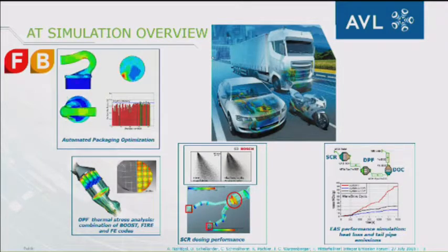Then a simulation solver calculates the uniformity of flow. Value one is ideal uniformity, and we have set a target of 0.85. Finally, a genetic algorithm is used to optimize the geometrical parameters to reach this uniformity level. So this is one of the possible applications.